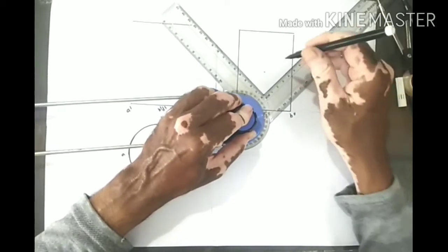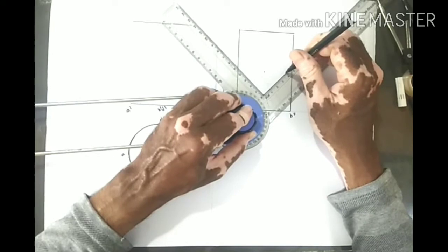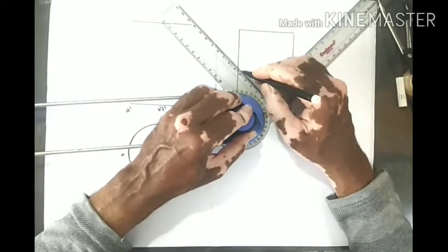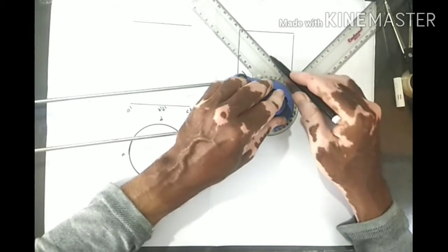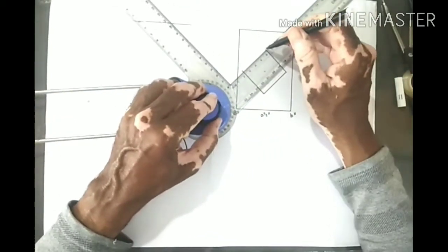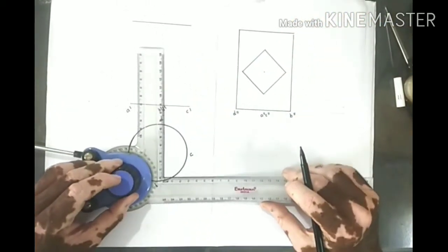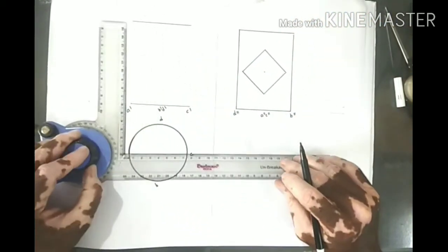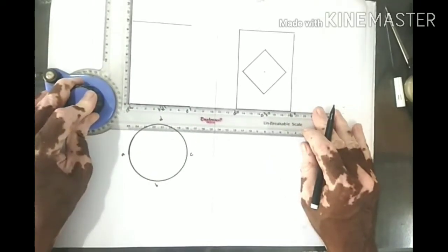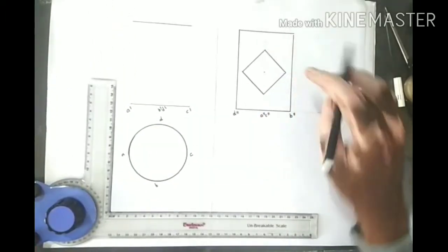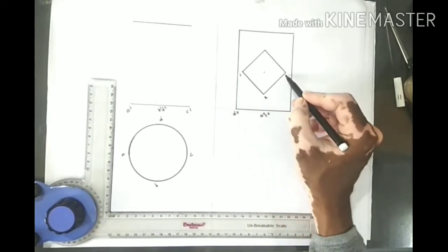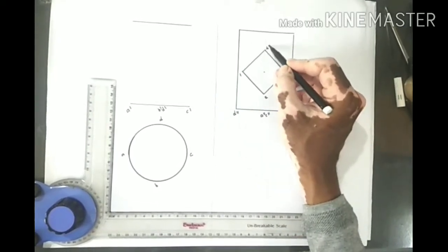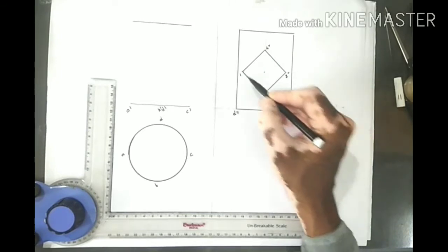So horizontal square prism base 40 mm side and everything is the same, means equally inclined to VP or HP and axis bisecting, etc. So here I am changing the size. Instead of 50 I am taking 40. So this 1, 2, 3, 4 double dashes because it is side view.